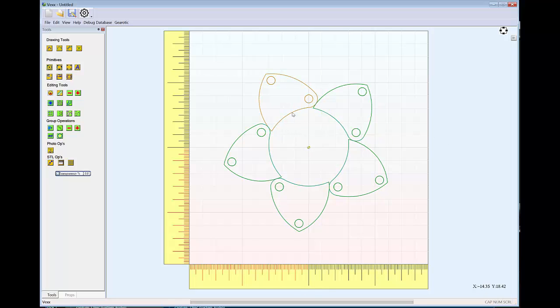So we need a circle which is going to surround these, which will be the inner part of our ring. So I'll select 0, and I'll draw a ring out to about here. And there's our inner ring. We'll need another one for the outer part of the ring. This will be the largest point on our mechanism. And here we are. And it has a radius of about 65 millimeters. So we're about 130 millimeters complete mechanism size.